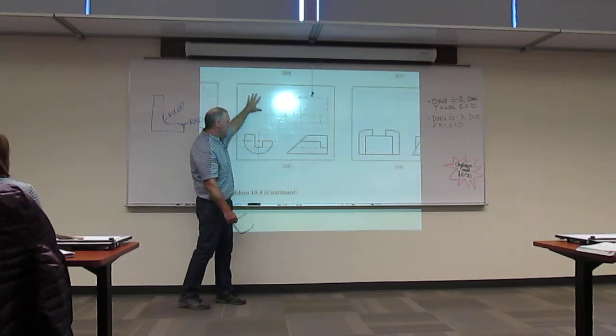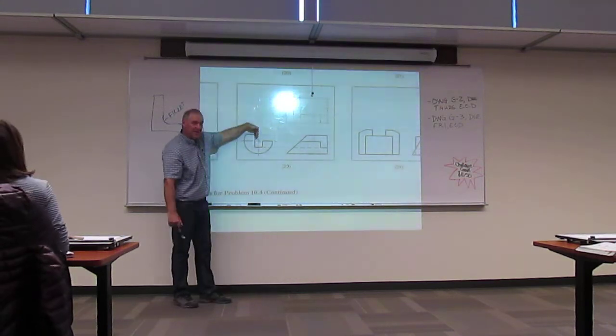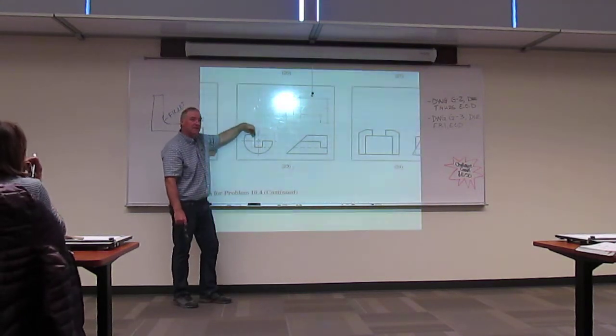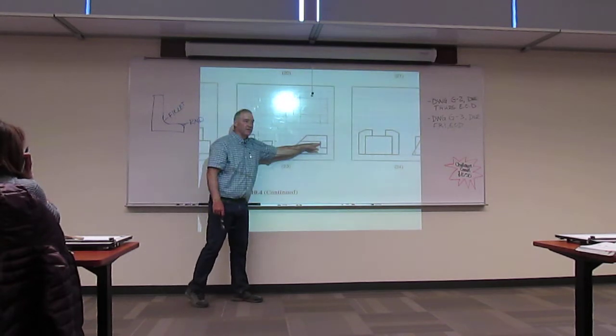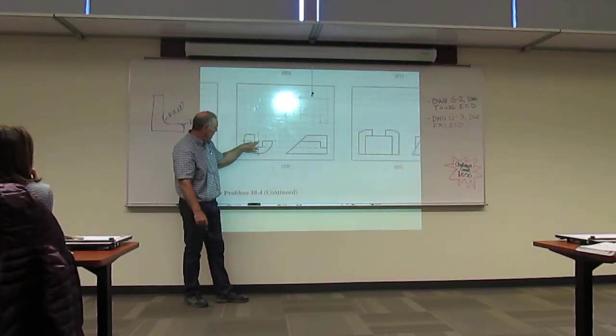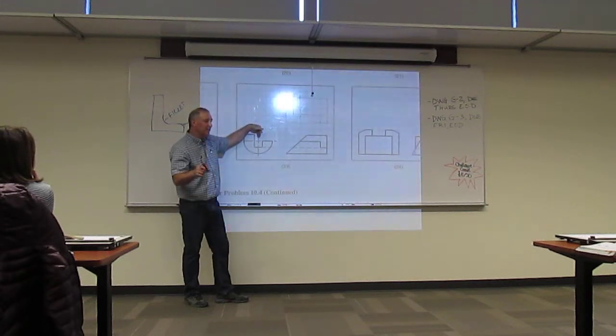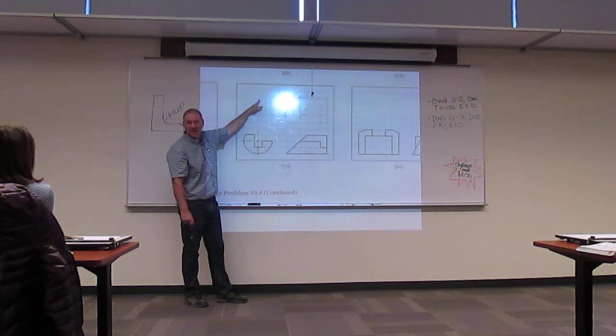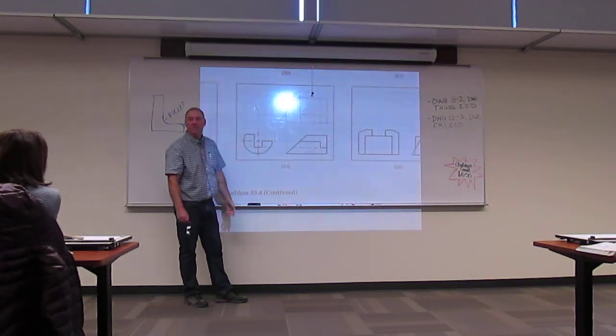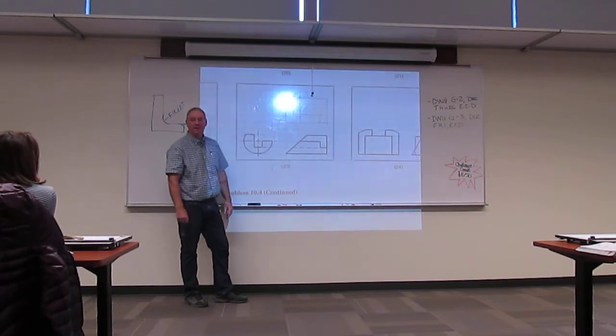Now, when I come to the top view, I will be looking here. So I'm looking perpendicular to the long axis, right? Okay. Because my long axis is this location. I see it as a point here. If I'm looking perpendicular to it, the cut is 45 degrees, therefore, how will this appear in the top view? Circular. Okay. It's a circle, it's not an ellipse.